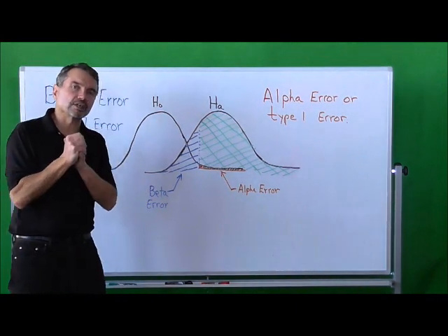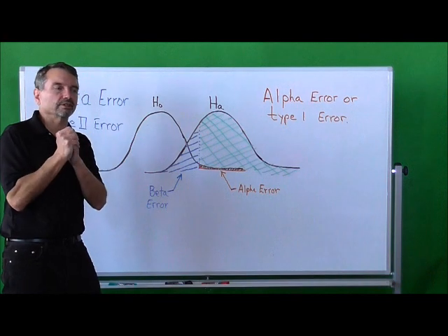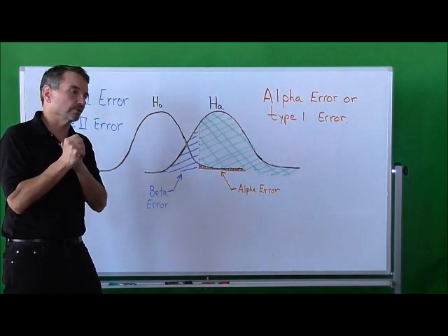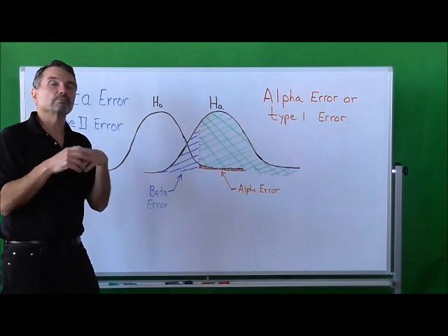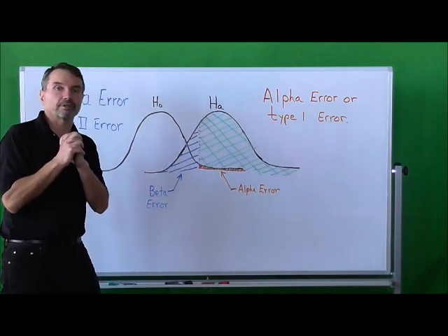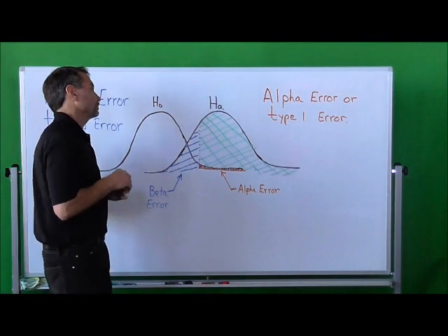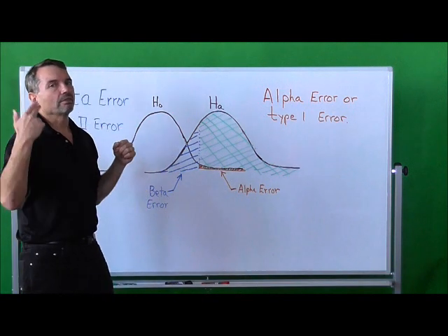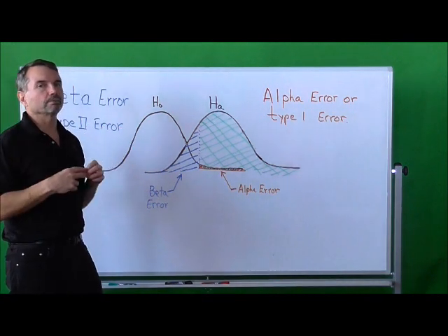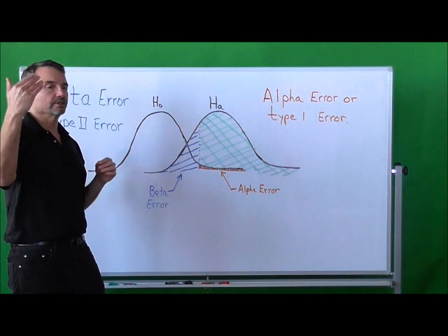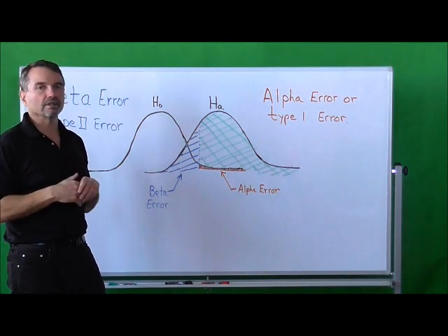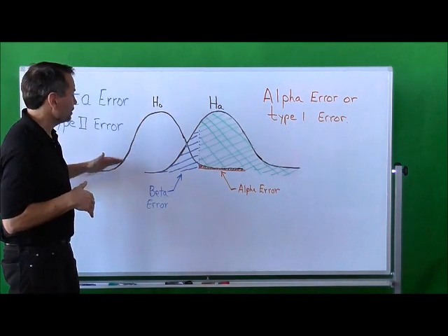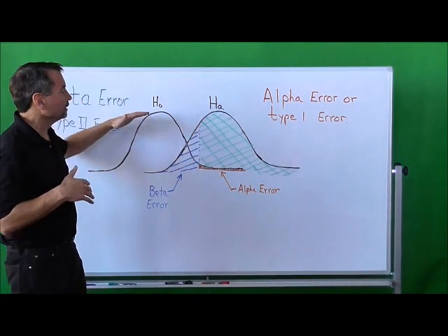And let's take an actual example. Let's say that we wanted to put a new product in there, or a new supplier came in and came up with a new product mix that we wanted to use, but it's a more expensive product mix. So consequently, we want to prove beyond reasonable doubt that the new material we brought into the process is going to give us an improvement in the yield coming out of our process. So we take our process and we measure it over the 3-month period of time.